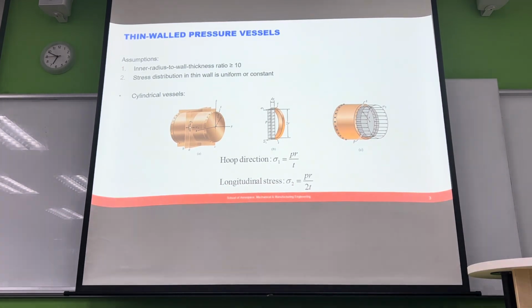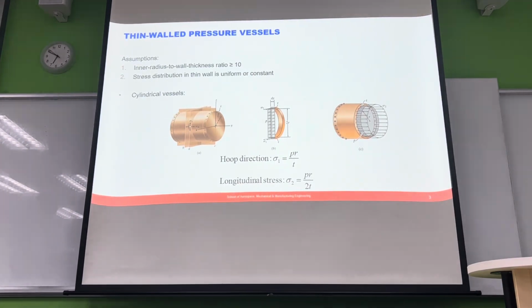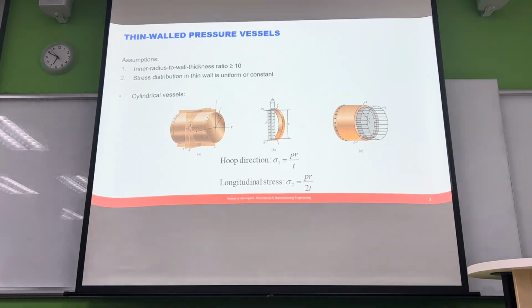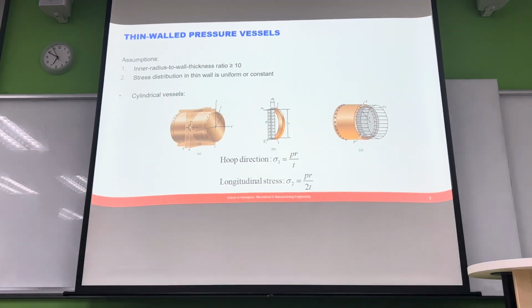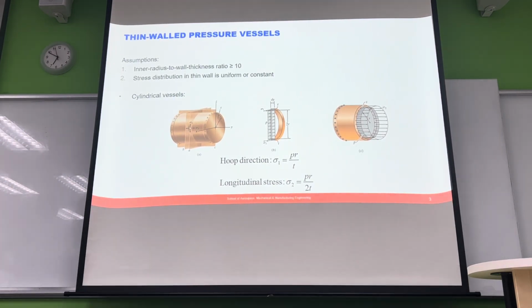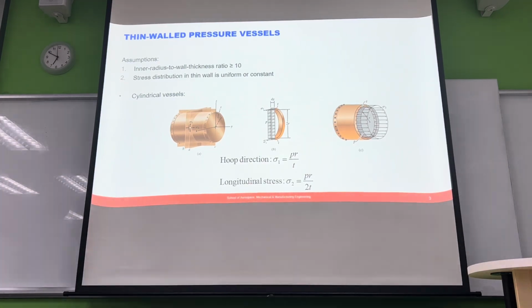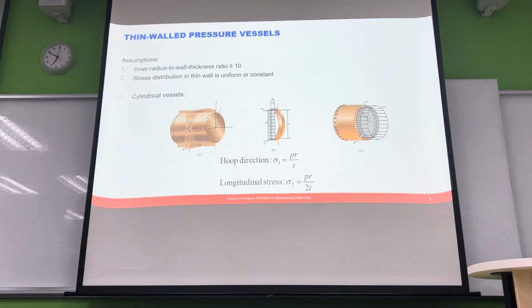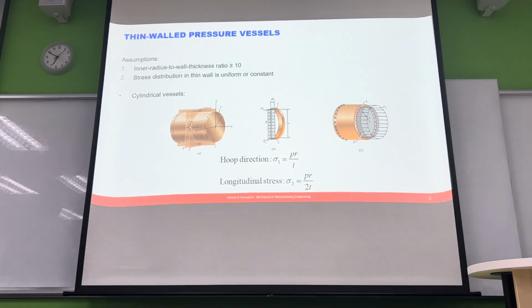So just like, if I move 1 meter forwards and then 1 meter to the left, I haven't moved net 2 meters. I can't add that 1 meter to that 1 meter because that is a vector, right? So these two vectors, the hoop stress and the axial stress, or the longitudinal stress, you can't just add those two things together because they're acting in different directions.